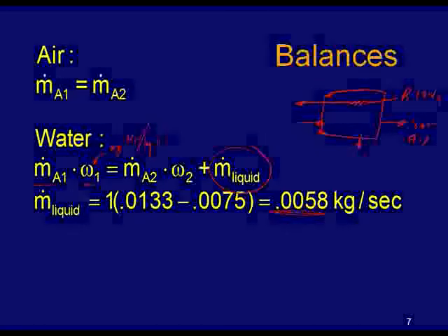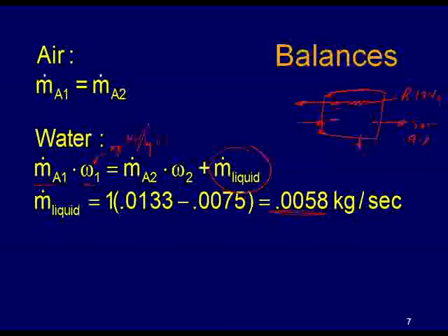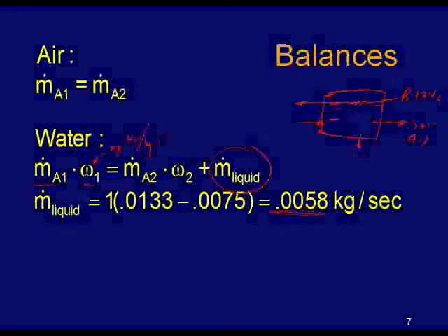While I'm on the subject, we need to make sure, this concept of a driving force for a heat exchanger, you need to make sure that there's a delta T between the coldest air, which would be over here. There's some driving force for heat transfer, so the R134A must be, let's see, we said this was 10 degrees C. So the R134A must be less than 10 degrees C by some amount that allows for the heat transfer.